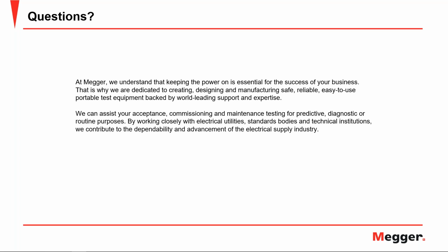So just think about a circuit breaker in operation. It may have a 480 volt service or whatever the voltage level is, and at that time, if a fault happens, then the current would be in hundreds of amps. So in those situations, you might be dealing with high voltage and high current at the same time. But this test, this offline primary injection test that we are talking about, is not a destructive test because you are using the low voltage and high current concept.